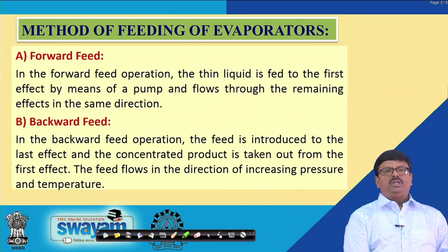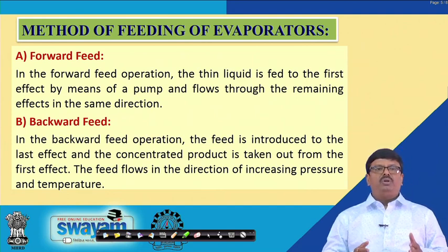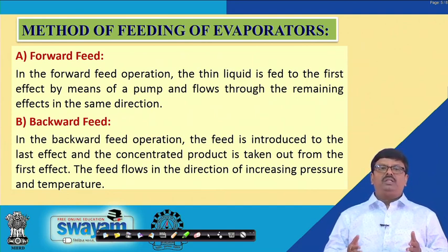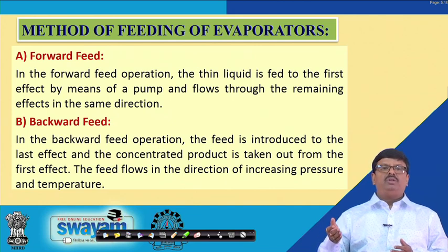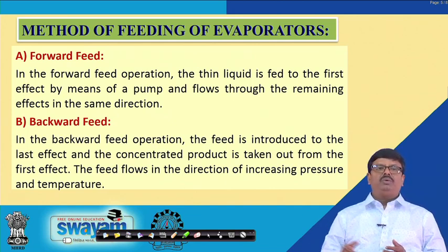Method of feeding of evaporators. So, these are the different kinds of feeding methods. Forward feed means where the thin liquid is fed to the first effect by means of a pump and flows to the remaining effects in the same direction.